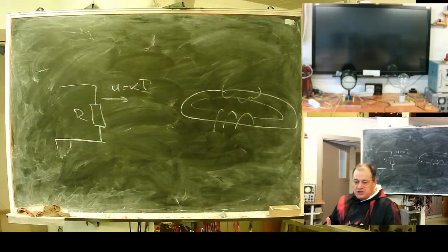The other machine this time slows down and lays down the already processed part. Without energy flow, the machine that speeds up takes energy from the network, while the machine that slows down wastes it on load resistance, on ballast. So energy is wasted. It's very lucrative to organize energy flow on the DC bus.